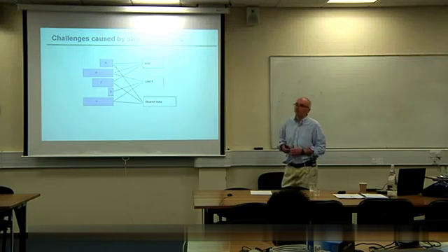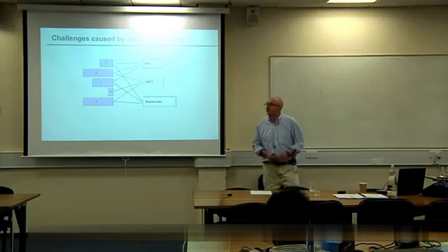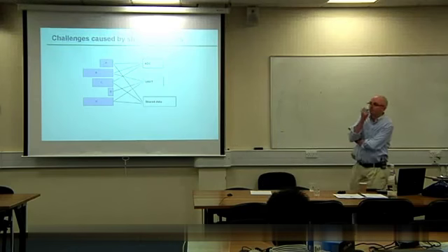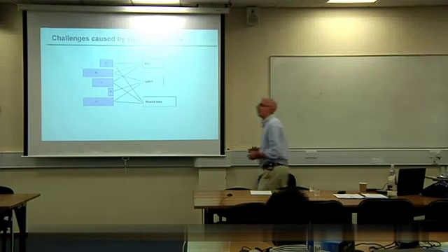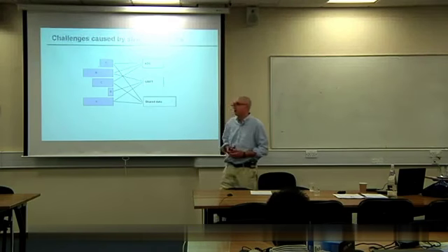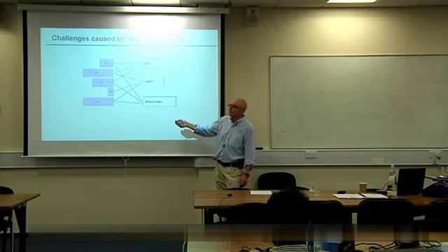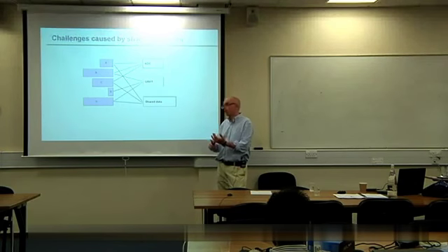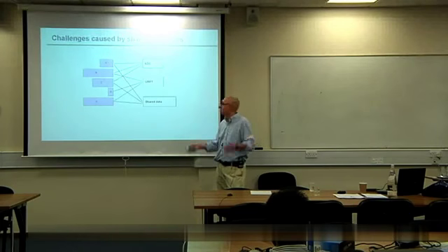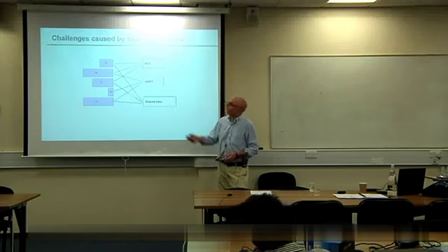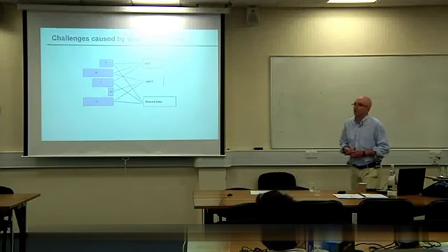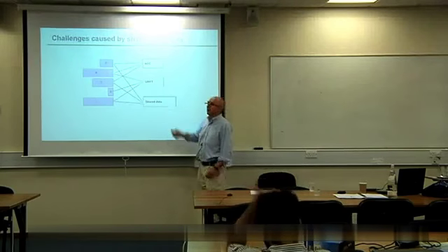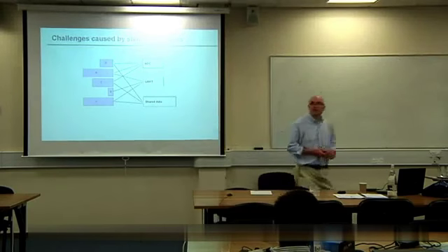And one way of doing that would be to say, task A might use channel 1 on the ADC, task B might use channel 2 on the ADC, and task C uses channel 3, whatever. Suppose we just give task A responsibility for the ADC, and we don't let any other task access the ADC. Does that solve the problem?